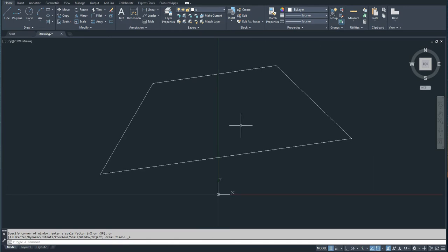Next step, guys. Now, what is this? This is an object in AutoCAD, and this object's type is line. For a line, as you see, guys, we need the first point and the second point. And by the way, if we click on the line, it will give us 3 points. This point is the end point. This point is the other end point. And this point is the mid point. I will use these points later to snap on these points or to make accurate connections between objects. Now I will click again, escape.